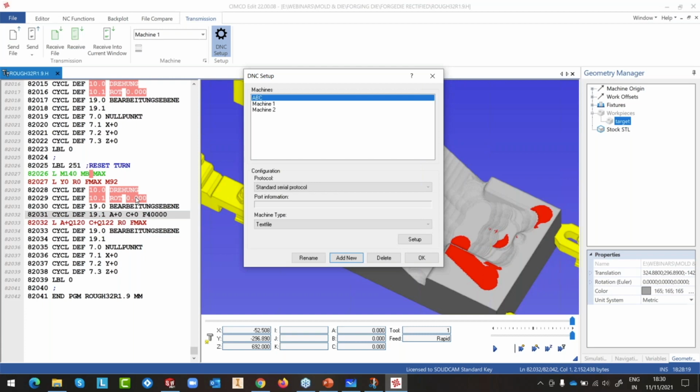Now, DNC is a very, very dangerous setup, especially if your DNC cable is running next to a voltage transformer or a stabilizer. If it is running on top of it, or very close to the voltage stabilizer, and if there is a fluctuation in it, there is every chance that when the program is getting transmitted, you can have errors in the code itself.